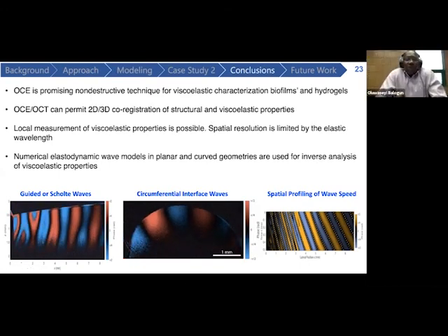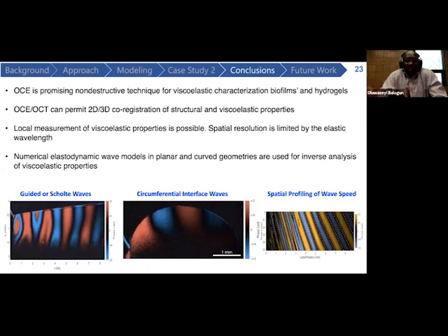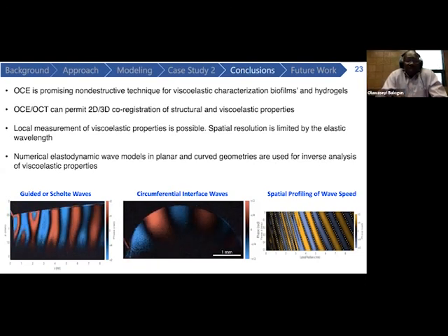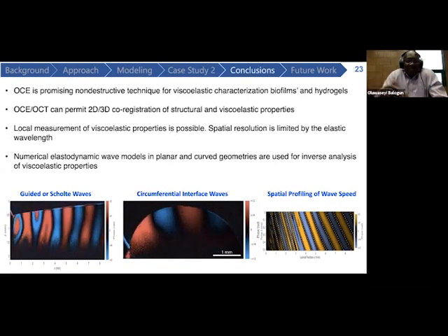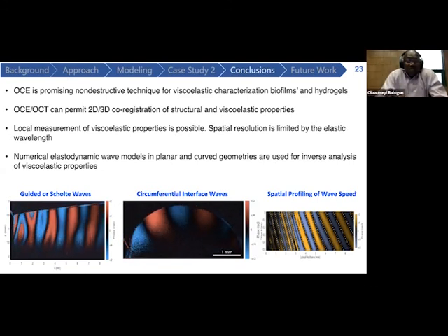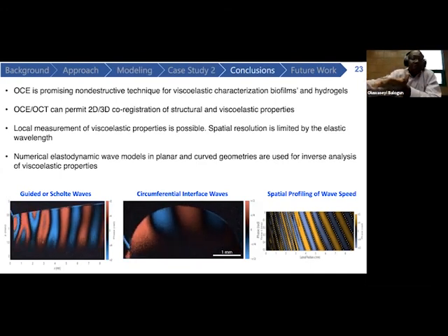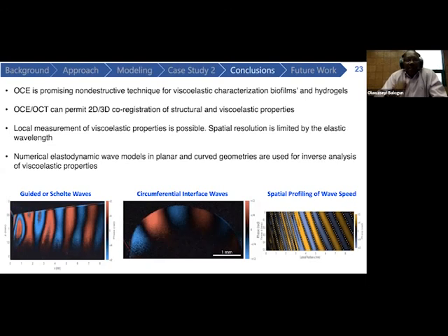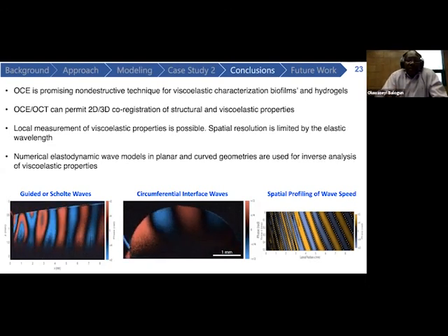Yeah, so what's of interest is both the instantaneous response, which we characterize in terms of the shear modulus. So these materials are incompressible. And so we're mostly focusing on the shear modulus, and that actually controls the deformation of these biofilms under flow conditions. It's a property that controls how this biofilm deforms.